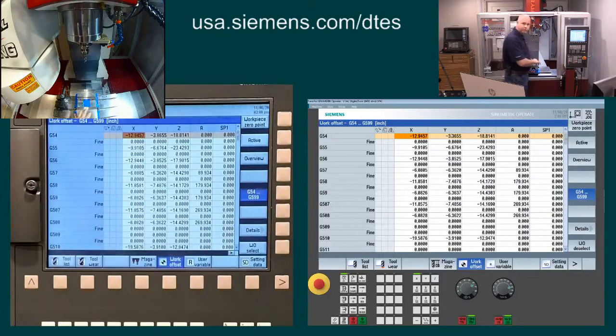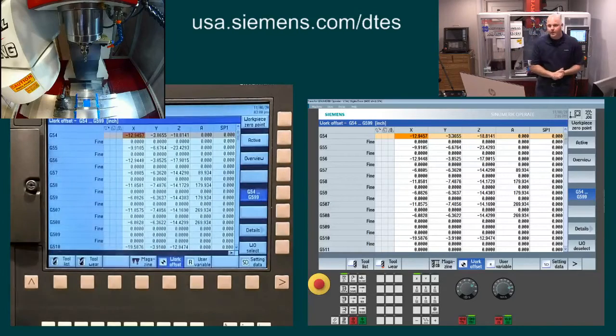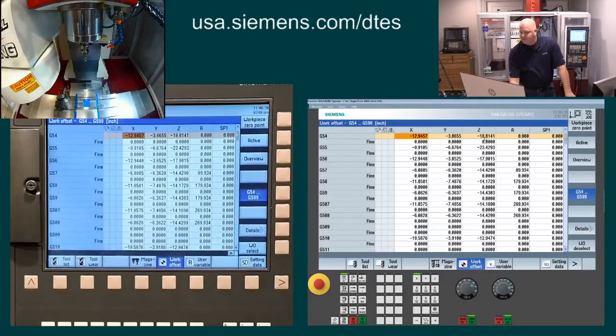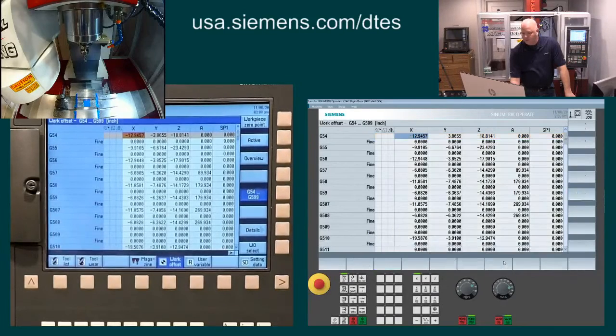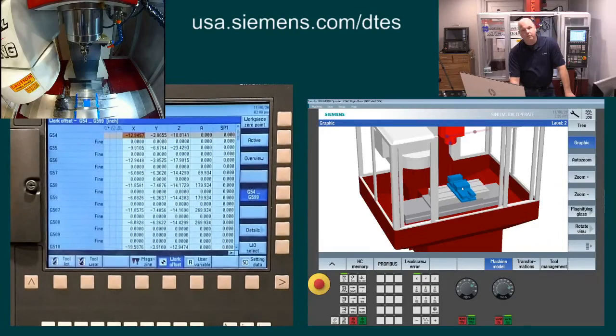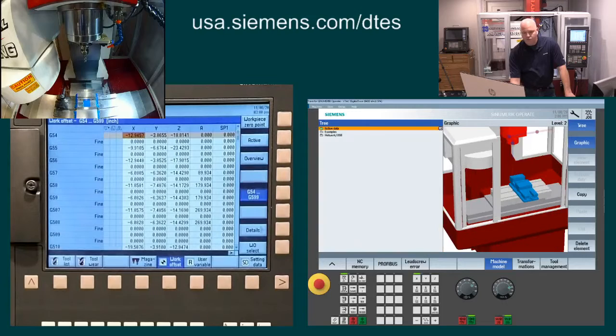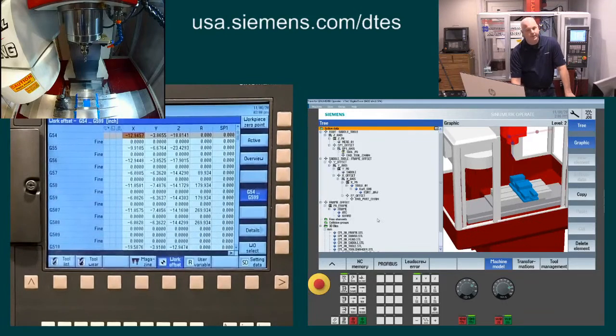So once I had the numbers here, if I did my job properly when I built this digital twin, well, I could immediately plug the exact same numbers over onto this side and then use these numbers when I positioned my vise, my work holding, into the space of this model. Now it gets dropped in through our kinematic tree here. So I go to my vise.